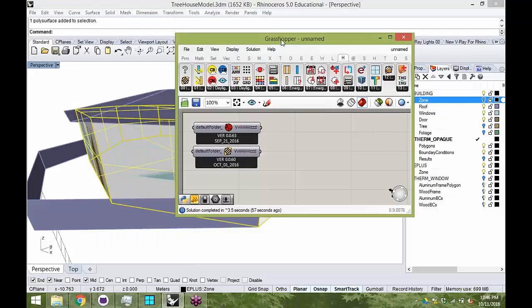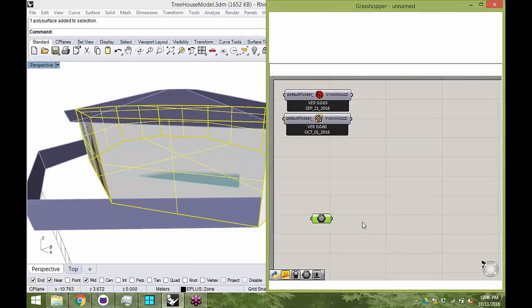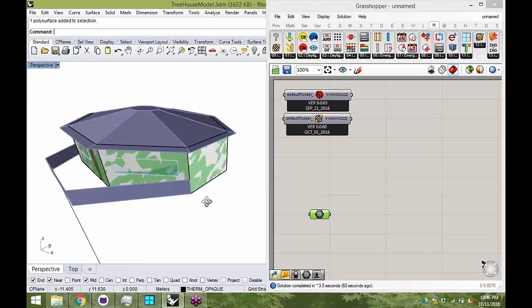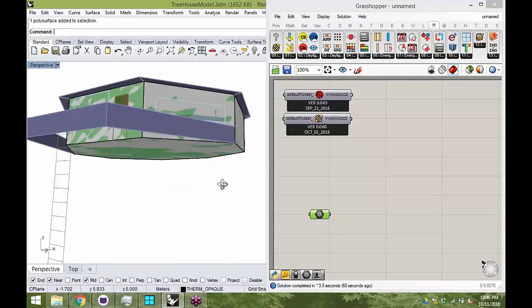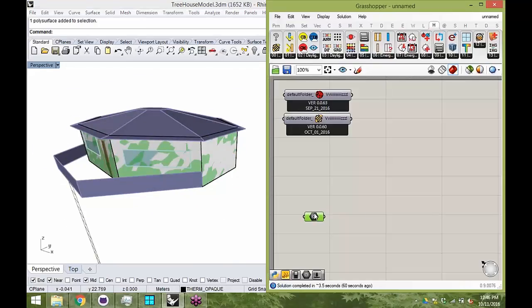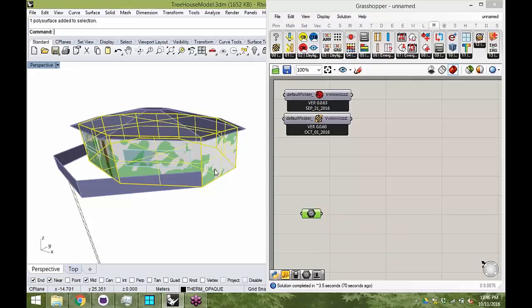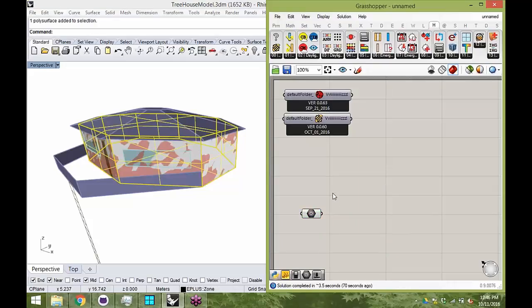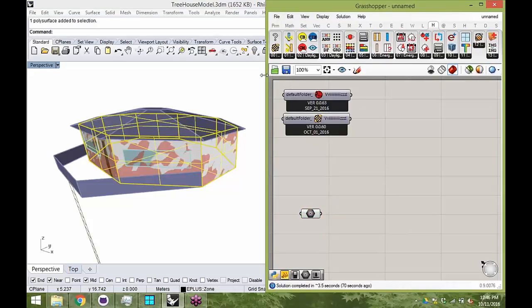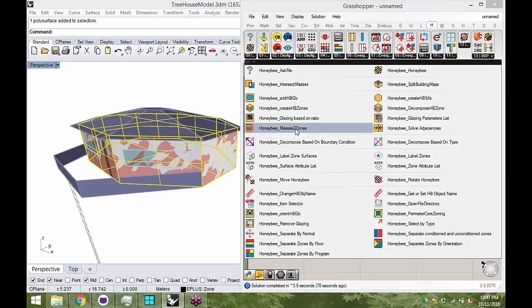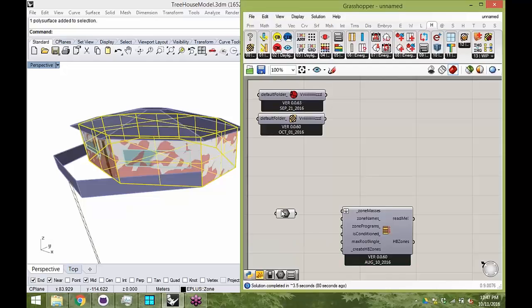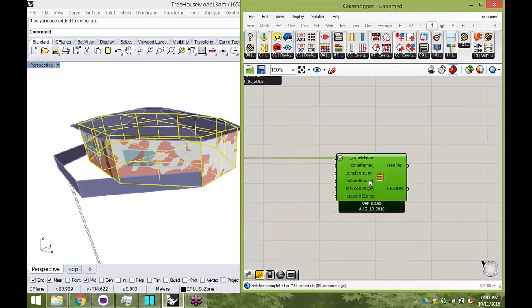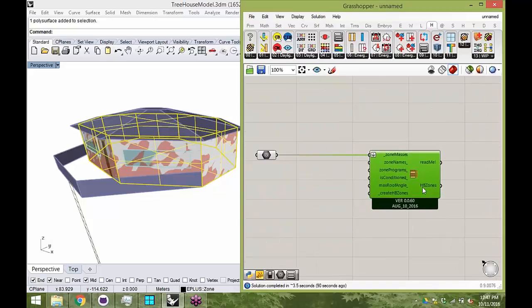Let's bring that into Grasshopper. We're just going to set one geometry. The first thing we need to do is this: in Rhino it's just geometry, that's the only information associated with it. But energy models require a lot more to actually run them. We need schedules, a program, constructions, wall constructions, and everything. So I'm going to drag and drop the Honeybee Masses to Zones component onto the canvas, which is under the 0 tab. This allows us to take any closed volume like this and convert it into a zone with all those properties auto-assigned, basically.